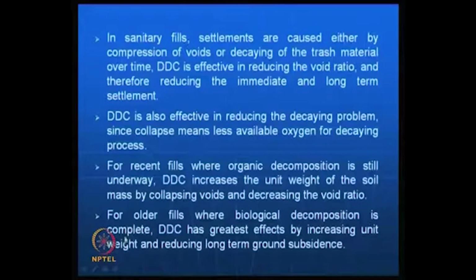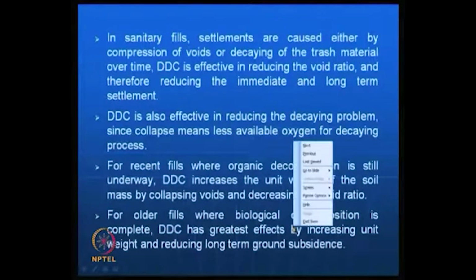So definitely this dynamic compaction is very helpful in reducing the settlements, and in some places where these fields are old, biological decomposition is complete, dynamic compaction is very useful in increasing the unit weight and in reducing the long term subsidence. This is another important point.